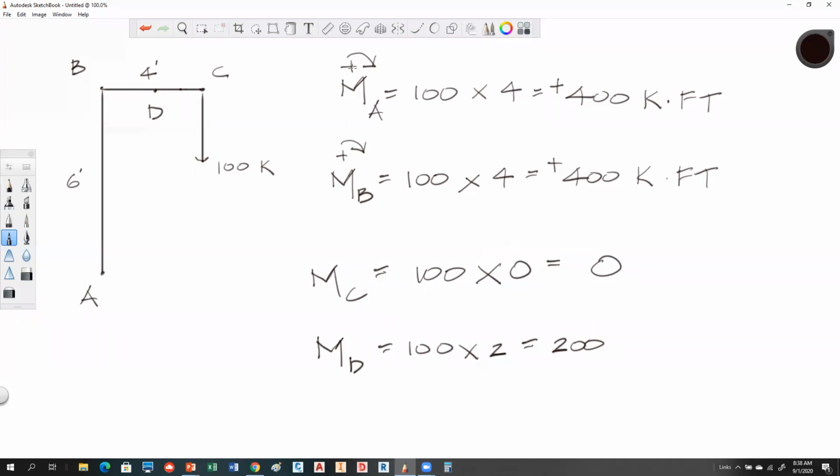Okay. So this is a really, really important concept. It's actually pretty simple. You just have to remember that the distance has to be measured perpendicular to the line of action. And if the line of action comes through the moment point, it drops out. It goes to 0, which is going to be a really good thing for you to understand later on, because you're going to be able to utilize that to get rid of stuff. We want to simplify every time we can. Is everybody okay with that?